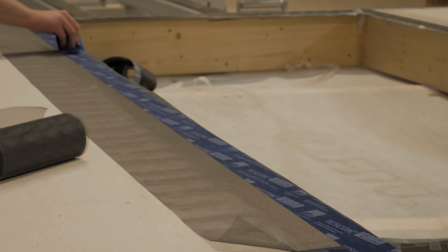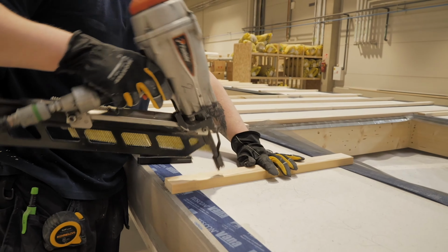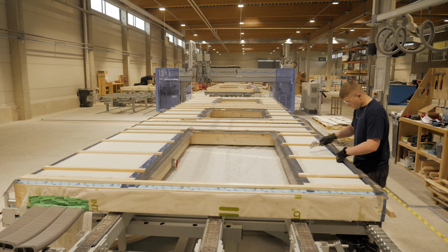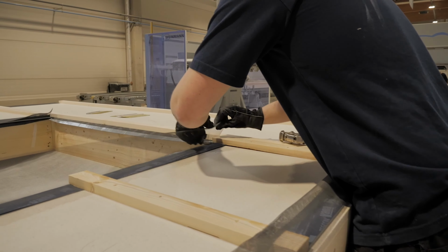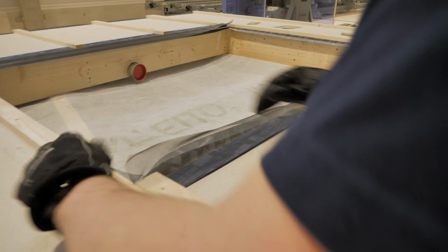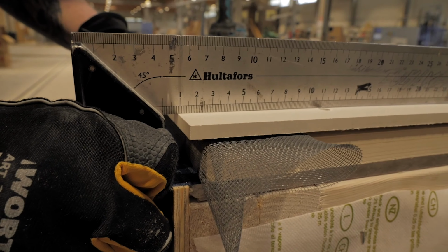Next, attach wood slats to the wind barrier board. Note that the slats need to be secured on point. Ensure the slats are precisely secured, fixed. Wrap and secure the loose ends of the previously added insect net around the slats. Perform a final check to ensure everything is properly installed and secured, preventing any moisture or insects from entering the construction. Once confirmed, you can begin assembling the facade panels.